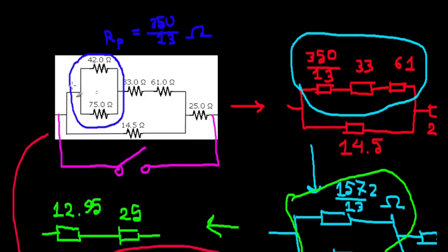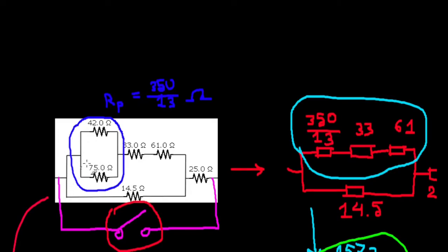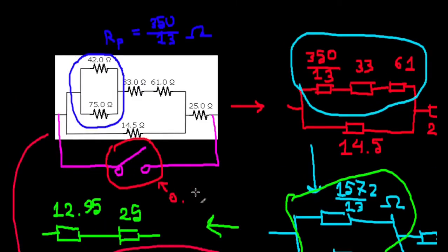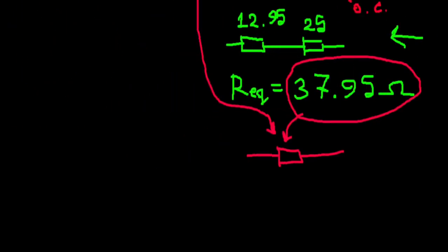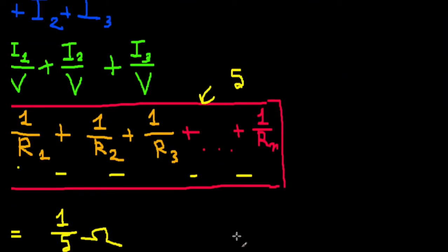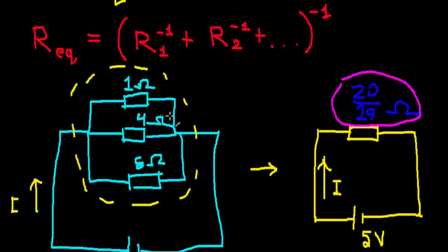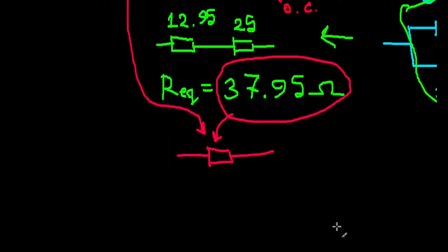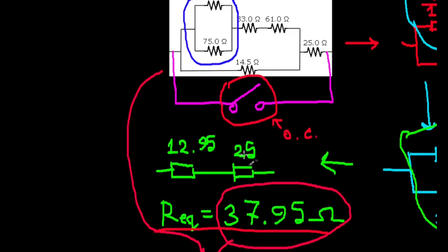When it's open, like we discussed in the last video, this doesn't really affect anything. Having an open circuit, or a gap, an infinite resistance in parallel with this whole thing, which is basically another resistor, wouldn't affect anything. I'd really encourage you to take your parallel resistance formula and see why it doesn't change anything to have an open circuit. Use the fact that the resistance of an open circuit is basically infinite. If that's the case, then the equivalent resistance is the same as before.